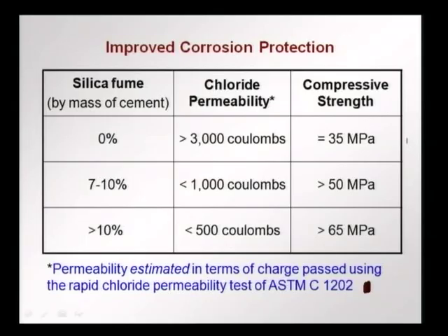other effects. We find that a concrete with no silica fume, 0% silica fume, say with a strength of about 35 megapascal, in this test could pass about 3000 coulombs of charge. Same concrete with 7 to 10% of silica fume, the charge passed is reduced to less than 1000 coulombs, the strength also goes up to 50 megapascal.